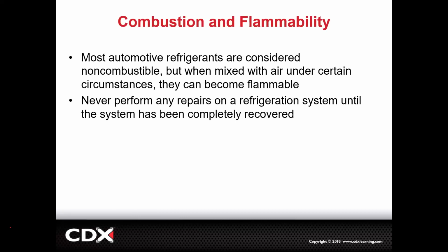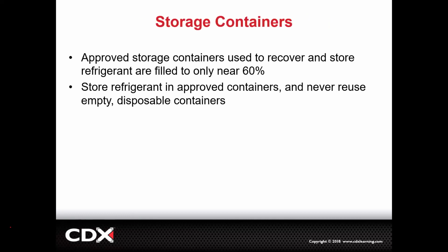Make sense? So you just got to be aware with smoking or torching or these types of things. You just really can't do that, especially when there may be any kind of leak or something. Okay, makes sense? So when we go to work on it, we're going to completely recover it for our safety, but also, it's actually illegal to discharge that without recovery. So you need to do it for the environment and for your safety. You definitely need to do it.